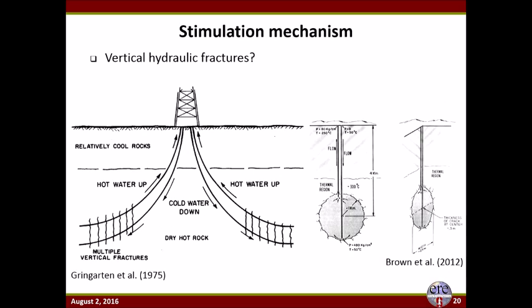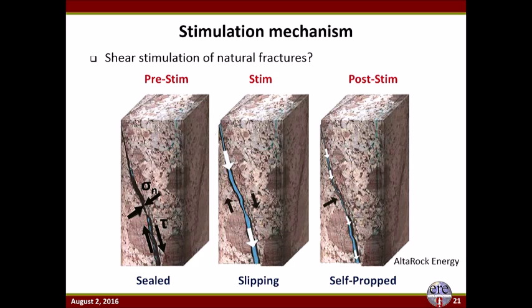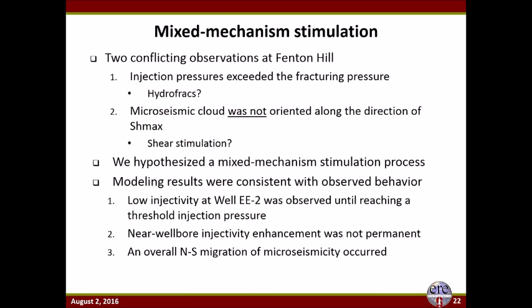Were these vertical hydraulic fractures propagating through the formation? This was actually the original design of Fenton Hill. Others believe that perhaps it was shear stimulation that was dominating the overall stimulation process, where slip on natural fractures increase their permeability. And really, if you look at the data, there are two contradictory data sets that these different groups were using to support their ideas.